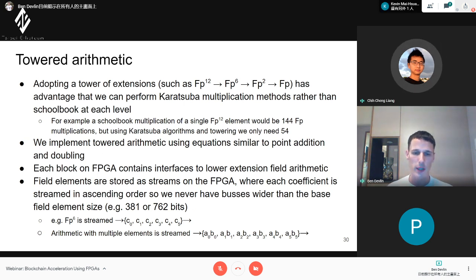No. On the FPGA, we can actually say the data bus is 381 bits, because we can program it. So there's no 3 bits of overhead. We specifically say 381. You'll see we actually make a coprocessor. Because we have to interface to a software memory region, we do add a few bits, but we use these for metadata. I'll show this in a second. Okay, thank you.